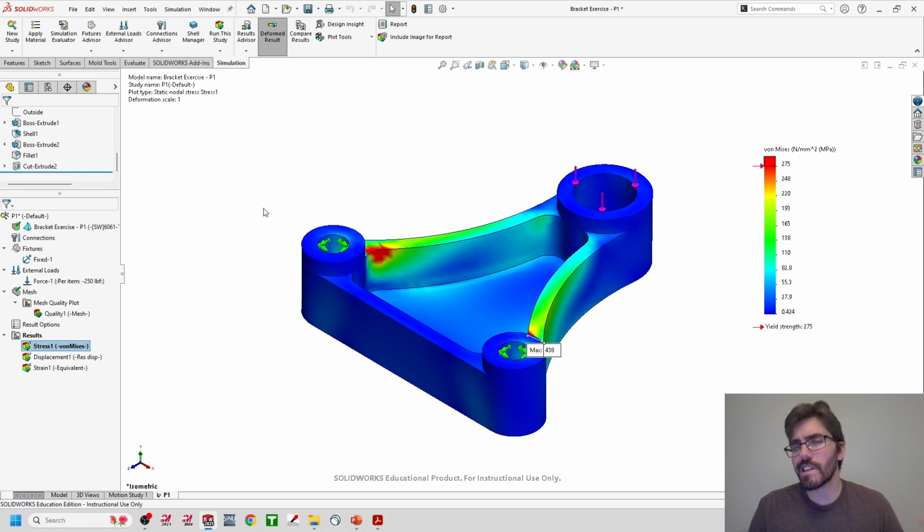And then I just, again, want to return back and explain this chart here one last time as we move into creating another plot. So I am going to recommend or encourage you to always update this chart here to correlate with the yield strength value of whatever material that you're using, mostly because I want you to stay within the realm of elastic deformation. So that when you apply loads and forces, you want to make sure that the part or component always returns back to its original shape or size.